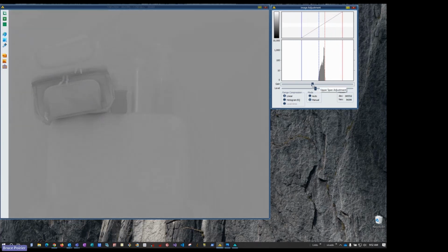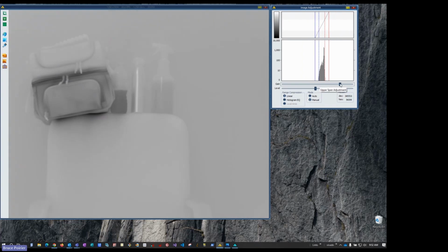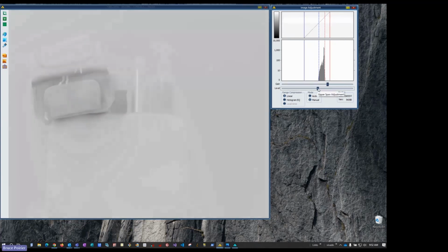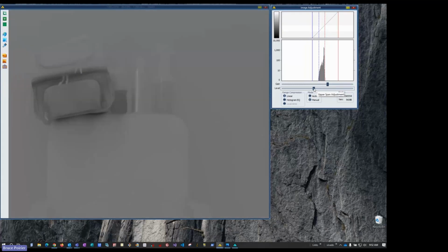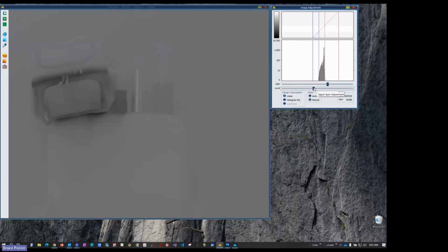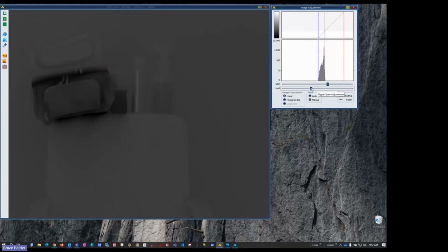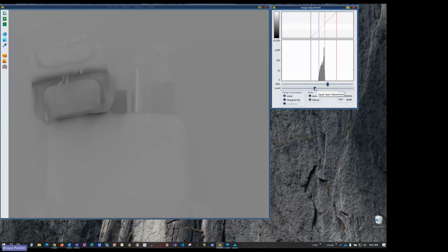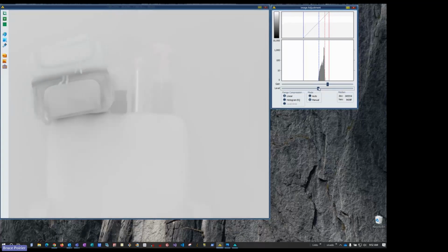If you move the gain indicator, the red and blue manual adjustments move in and out, but they stay around the same center. If you move the level, it moves both values either to the right or to the left. If you move to the right, the image gets darker. You can see that by the band moving towards the dark part of the palette. And if you move to the left, the image gets brighter.